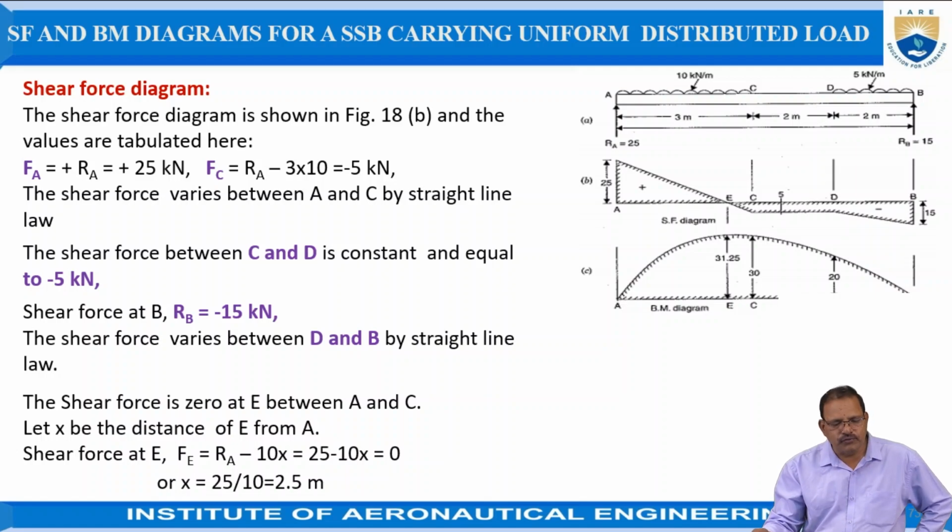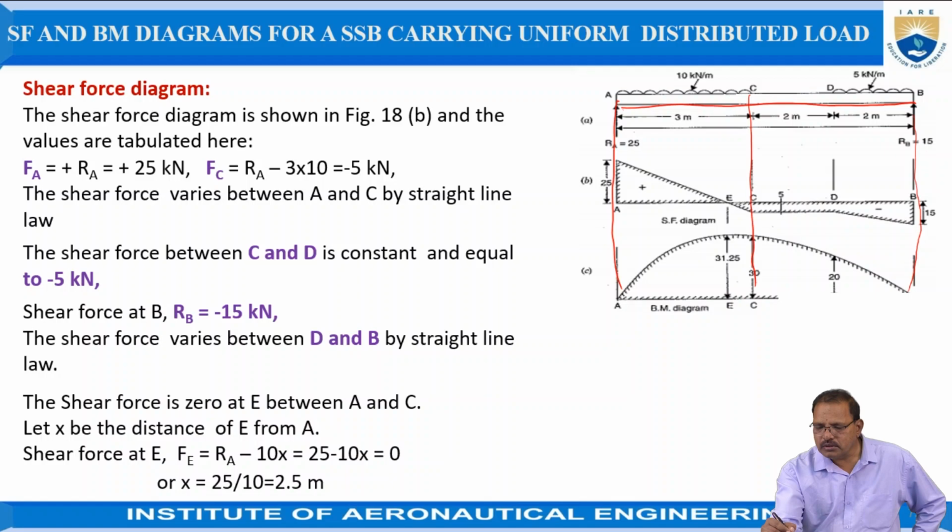Now, shear force diagram. First of all, represent the beam as per a suitable scale, as shown in the figure here, and represent the forces which are acting on it. After that, draw the vertical lines passing through the points A, B, C, and D, as shown in the figure.